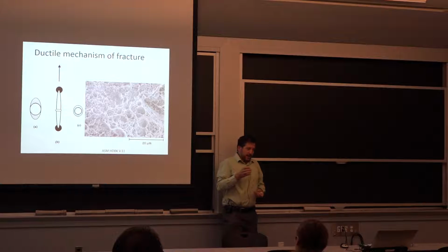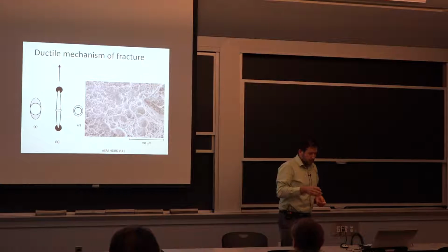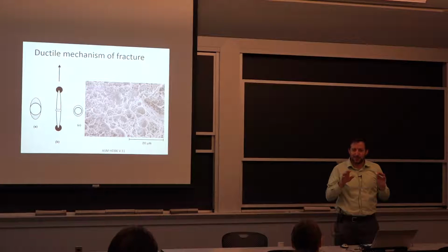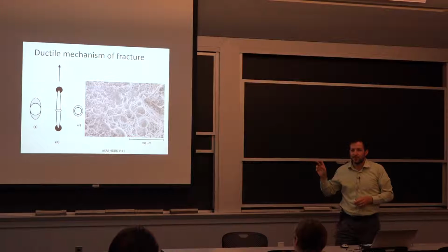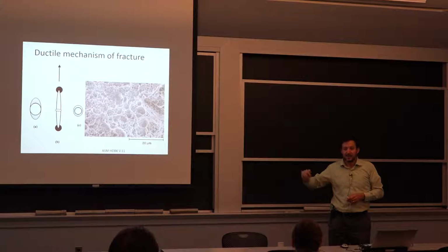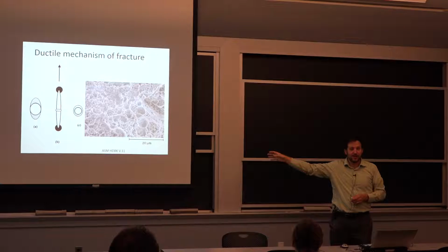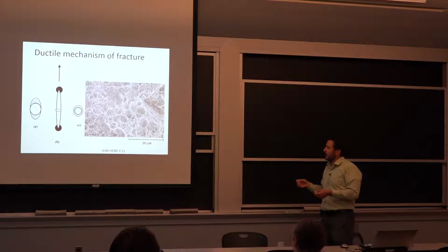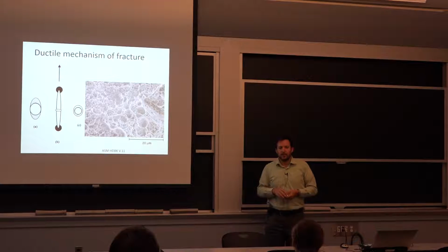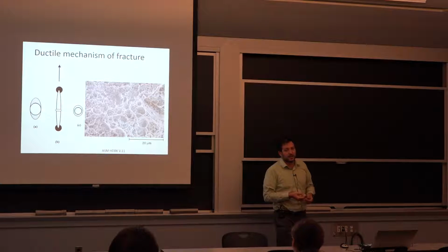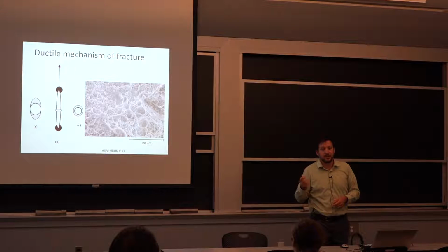So anytime that we have a fracture on steel, and I'm not kidding, this is very, very common, the first thing people want to know, because you have to go to a high resolution microscope to see these, is, did it fail in an overload in a ductile way? Because if it did, it means that you reach the material capacity. But there are a lot of other ways. If it happened in cyclic mode, then you don't see those features. If it happened because of environmental effect, cracking, embrittlement, you don't see this.